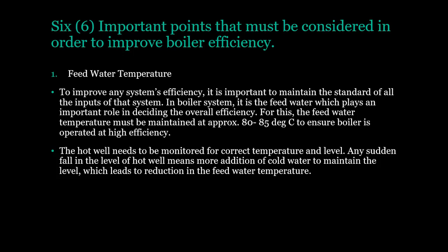Any sudden fall in the level of the hot well means more addition of cold water to maintain the level, which leads to reduction in the feed water temperature.